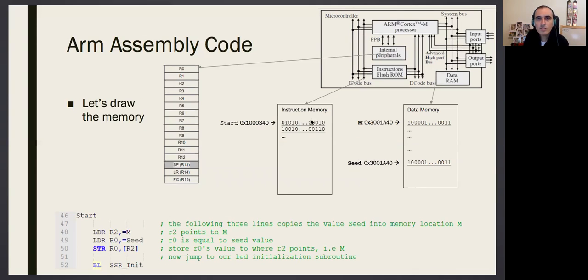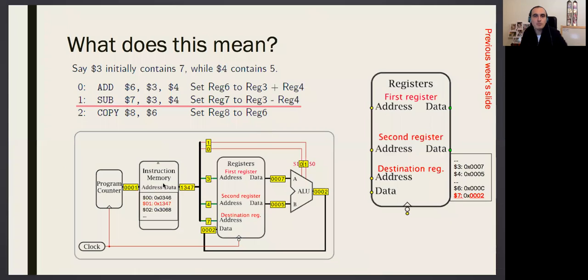So I've got in the instruction memory some lines, some binary codes. They correspond to my lines of code. So it is like this line, LDR R2, is coded such that it's a set of binary values. Just like this example. You remember? Since this hexadecimal, this binary code meant this, right?